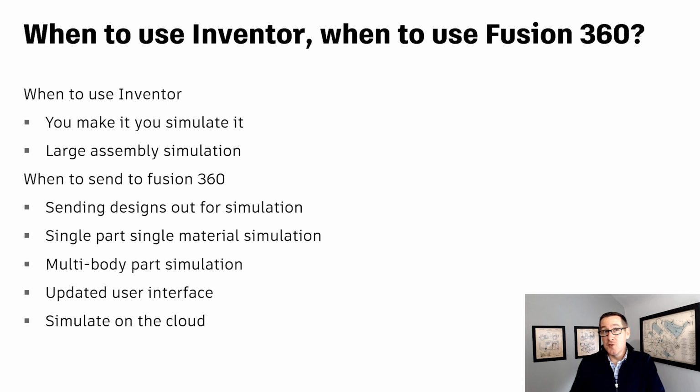Reason why you might want to use Send to Fusion is maybe you design it, but you send it out for simulation. Someone else, maybe a partner, is using Fusion 360 and they can do the simulation for you. Maybe you're doing a single part, single material simulation and you just want to get over to Fusion to do some cloud computing to leverage those options.